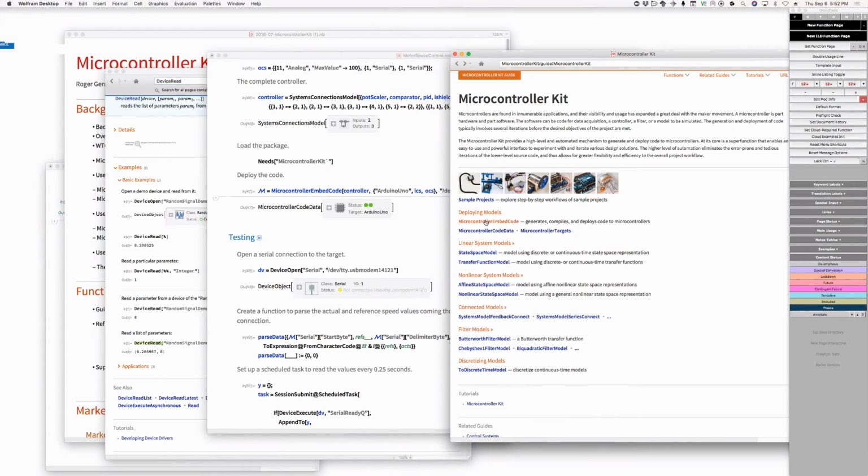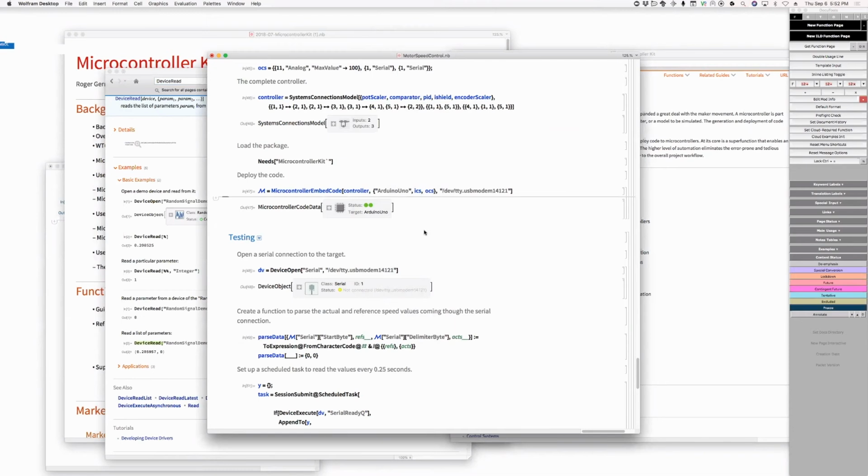No, but wait a second. Isn't it the case that the hardware of the microcontroller has a pin number 7? Yeah. What does pin number 7 do? It has an A to D on the other side of it. Or is that not the case? Or can you configure a pin to be either analog or digital? We can, yeah. They're GPIO pins. They can be configured sometimes for SPI, sometimes for analog. Okay, fine. The same pin. I get it.